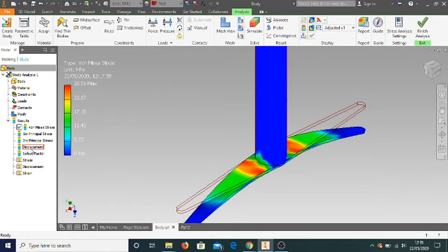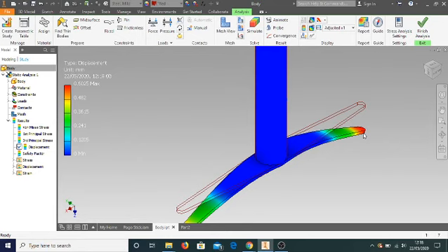We'll just look at displacement, and we'll see that the greatest displacement is at the end, which again makes kind of sense. That's what we would expect it to be. And we can once again look on here and see what that deflection would be. The deflection would be somewhere just over ½ millimeter. So it would be a fairly rigid foot pedal.